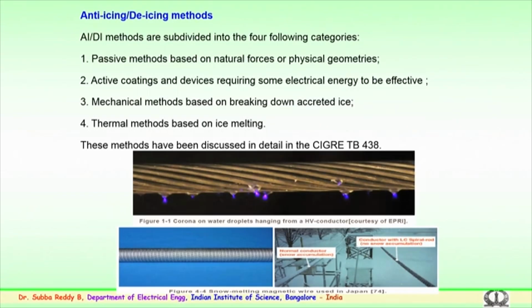Here you can see a few examples during the conditions where the surface of the insulators or the surface of the conductor has discharge activity. This shows that the droplets get accumulated over a period of time. Slowly the dust could form, and this dust can again contaminate the conductor or the insulator in the long run. So, this has to be prevented in the field.